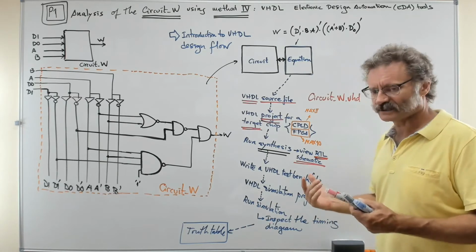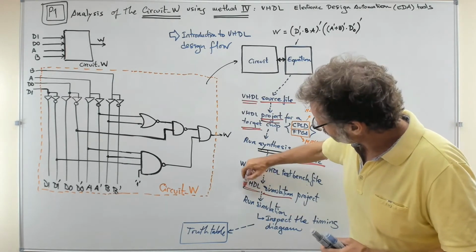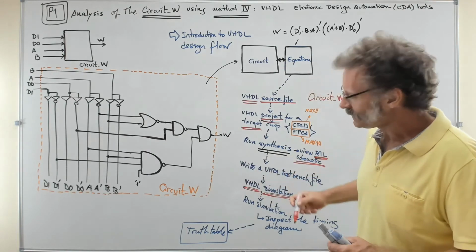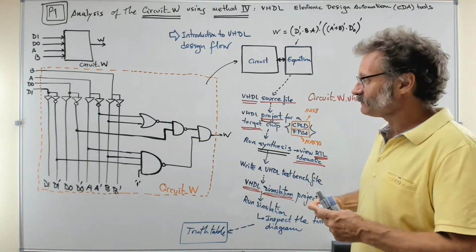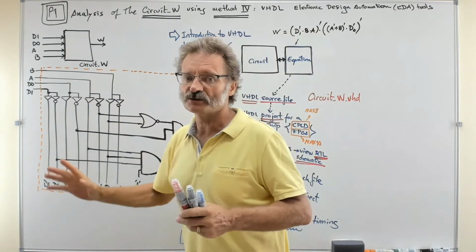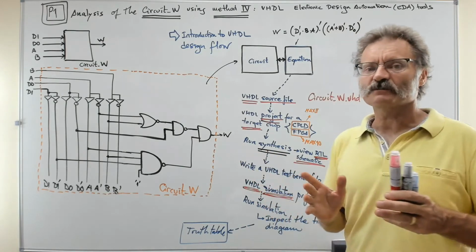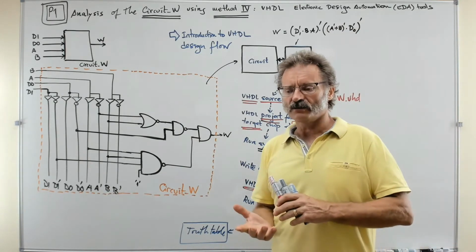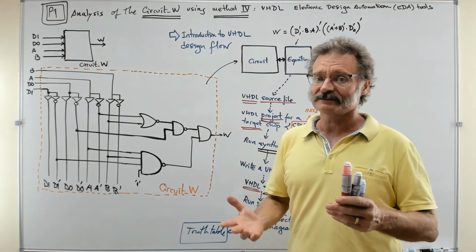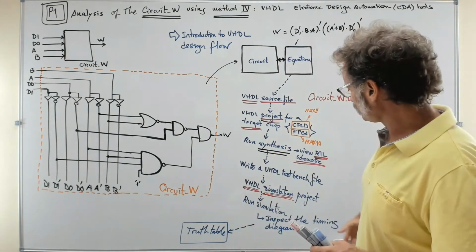This time, using VHDL techniques for simulation, you will get the truth table in the same way that you did using Proteus, applying ones and zeros as a stimulus to the inputs so you get the output. And if possible, let's consider all the stimulus here, the 16 of them, from 0, 0, 0, 0 down to 1, 1, 1, 1. So this is the next step.